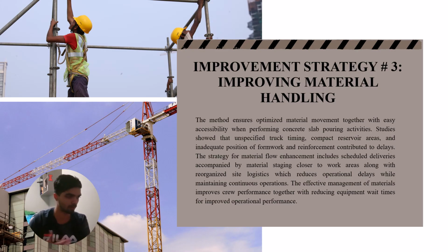Material handling seems to be a problem on the construction site we observed. In order to ease the material movement and accessibility during the concrete slab pouring, we observed issues on the construction site: unscheduled truck deliveries, where the concrete supply trucks were not scheduled effectively, and also compact areas for the material placements, where the tight layouts of the material caused difficulties in accessing necessary tools on time, causing delays in the construction. And also there was a problem in the formwork and reinforcement positioning that contributed to operational inefficiencies.